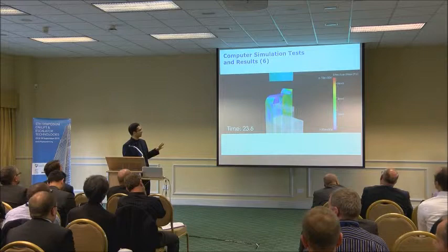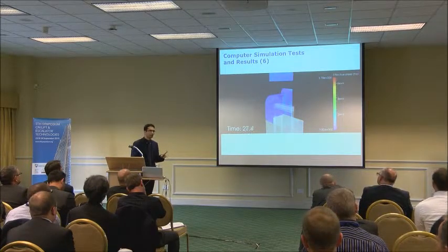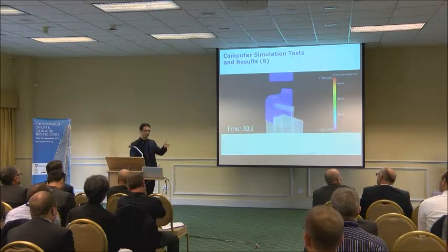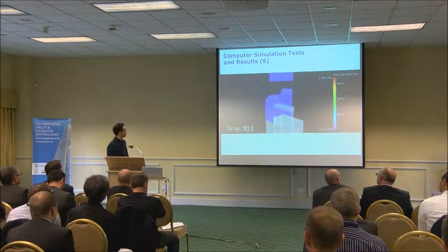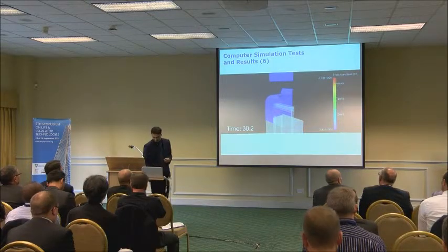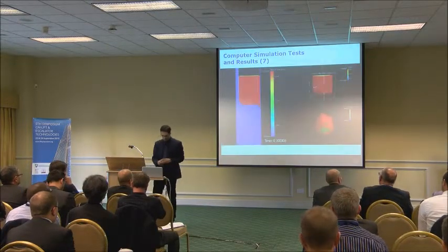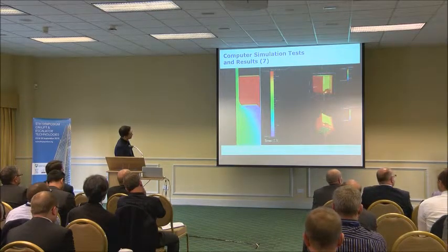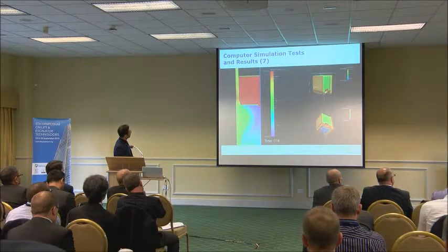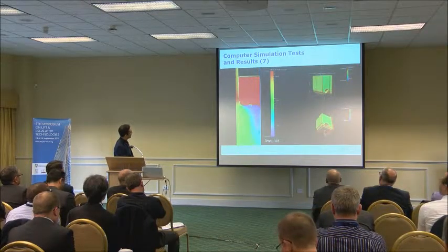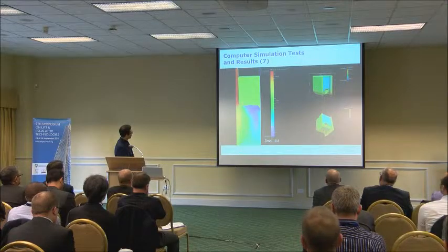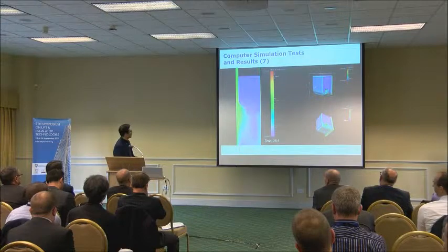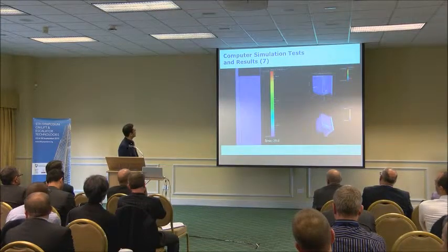I needed to make an assumption that the car is only traveling in two dimensions, so I ignored the Z direction. The car is only moving up, in the X direction, not the Z one. I made that simplification to make the simulation time slightly easier. Similar things happen at the bottom of the shroud too. We have the shroud at the bottom, the deformations and the pressure, and the air travel, or jet engine nozzle effect, at the bottom side is quite clear. This one is reaching up to about 6.2 at the top, about 6.7 roughly, and at the bottom about 6.2.